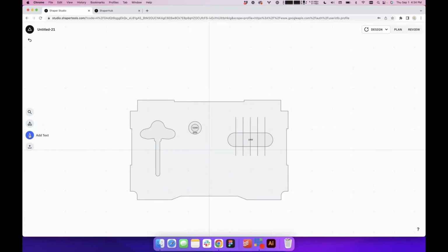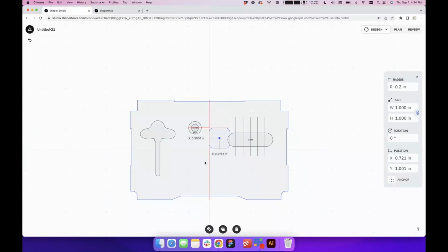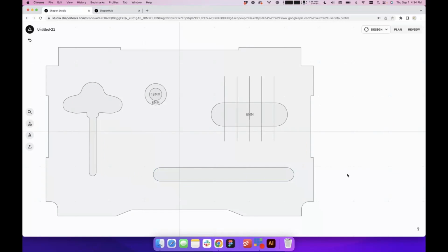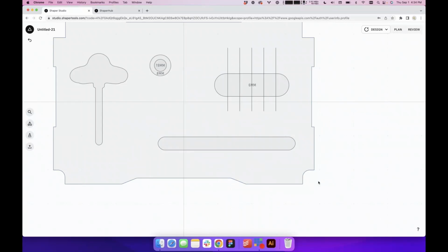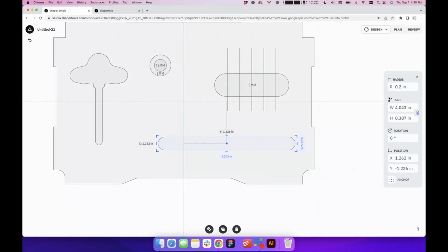I can always go in here, and if I wanted to customize this, put some engraving, I could do that, or make a shape for a different cutter or a different bit. Yeah, exactly. Like that 16mm router bit that we've got. So like, let's do this. What if you make a place for the shank that is 8mm wide, because it's got that 8mm shank on there? Yeah, and okay, let's do this. We want to work in millimeters, so we're just gonna switch over really quickly to millimeters. We didn't even talk about this before the show.